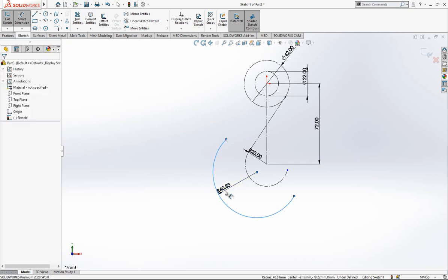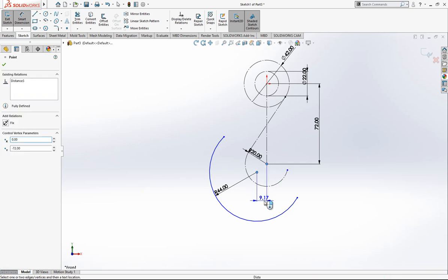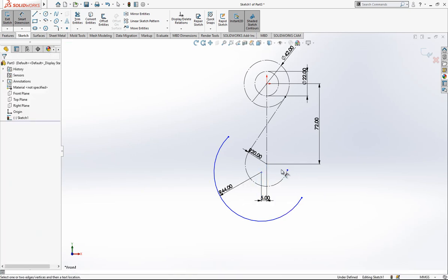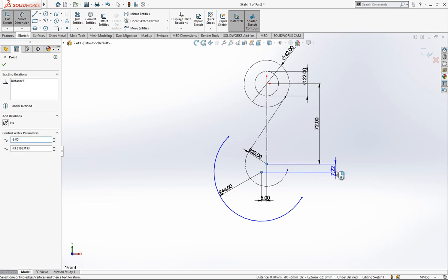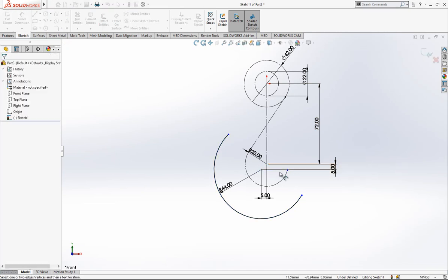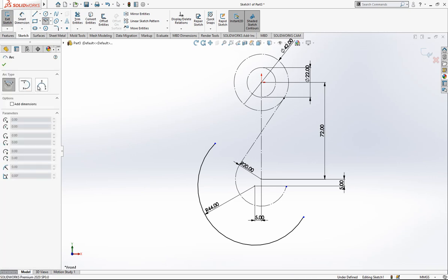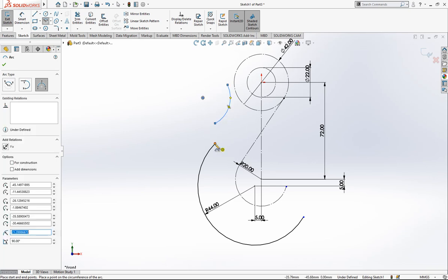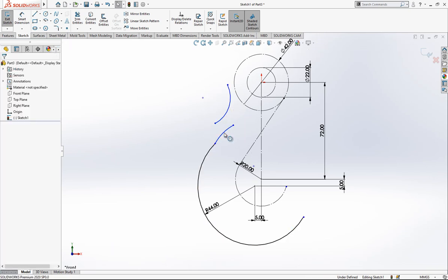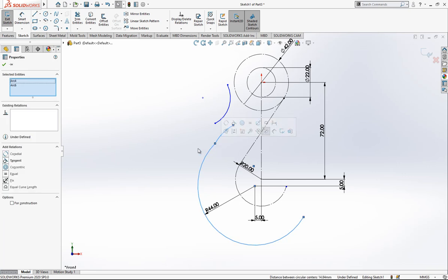Guys, this is 44. Also, the radius from the center 5 by 5 is aligned on this point. After this operation, I go create an arc, place one here and one here. These two will be tangent.